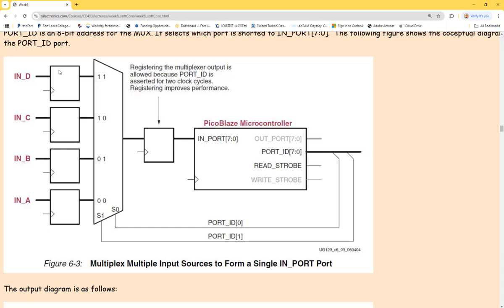Yeah, 8 bits. And you can have how many combinations from 8 bits of address? 2 to the 8 is what? 256. Yeah. So for 256, it's basically a 1 versus 256 mux.